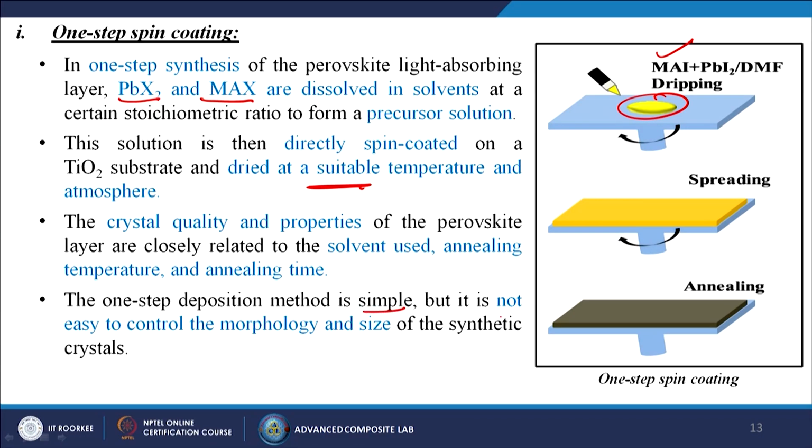So, the one step deposition method is simple, but it is not easy to control the morphology and size of the synthesized crystals. So, that is one kind of small drawback of this one step spin coating process.